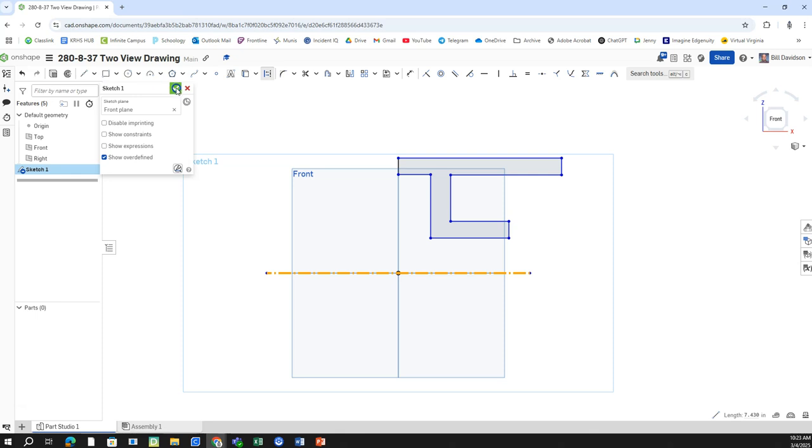All right, so I'm not finishing that sketch. Now I'm moving on to dimensioning things. I'm going to dimension from here out to here. I drew it at only 3, but it's supposed to be a diameter of 12, which means from the center line right there out to there is a radius. So I'm going to do 12 divided by 2.